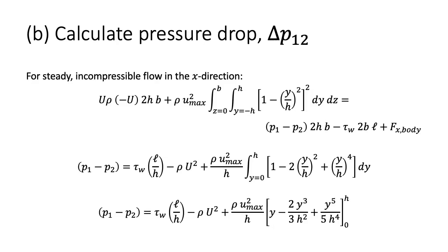For the right side, we must include all the surface forces acting on the control surfaces and all the body forces acting on the control volume. The first surface force we include is the pressure acting at section 1 and section 2 on the cross-sectional area of twice h times b. Note that the sign convention for pressure is that it is always acting inwards on our control volume. Also note that for a static fluid, pressure and normal stress have the same magnitude but opposite sign convention.